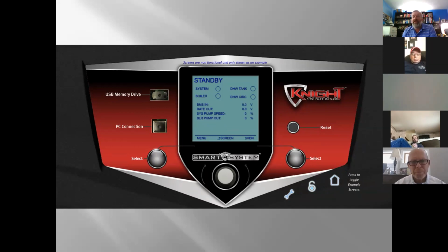So if I'm connected to a TechMark control, that's going to show up right here. Down at the bottom, my boiler pump output. The 2nd and 3rd generation controls have the ability to control a variable speed pump, and they'll tell you right there what speed they're sending out to it. In the 3rd generation, that variable speed pump comes right with the boiler.